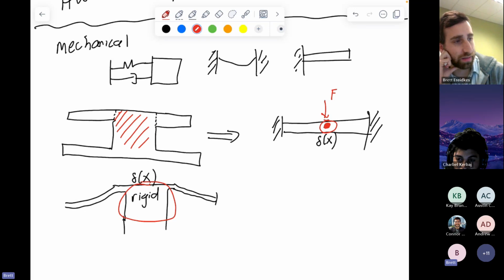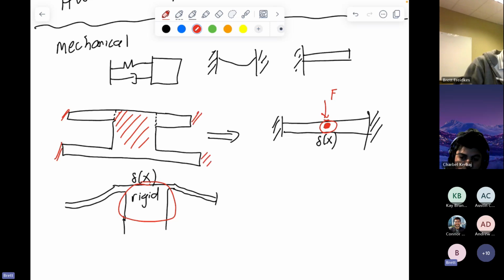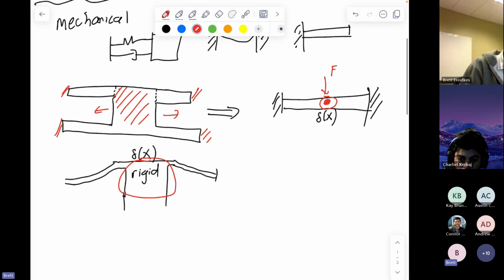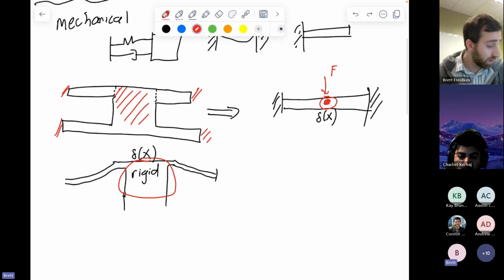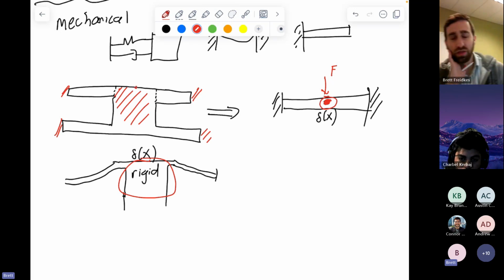Inside the block, not the outside bits, is why we can make the assumption. Inside the block, it just has the same exact deflection everywhere. We're assuming it's not twisting. Remember, if this is fixed on all four sides, based on the symmetry, it's going to be hard for this thing to deflect left or right in general because it's fixed on each side of those beams. And additionally, from a twisting perspective, there might be some twisting depending on how the beams are set up, but in general, we will neglect that case. So by assuming that the whole thing moves only up or down, and we model it as such here, where this beam can only move up or down, we'll say that the deflection at the center is identical to the deflection at the square and at the block. I hope that answers your question.